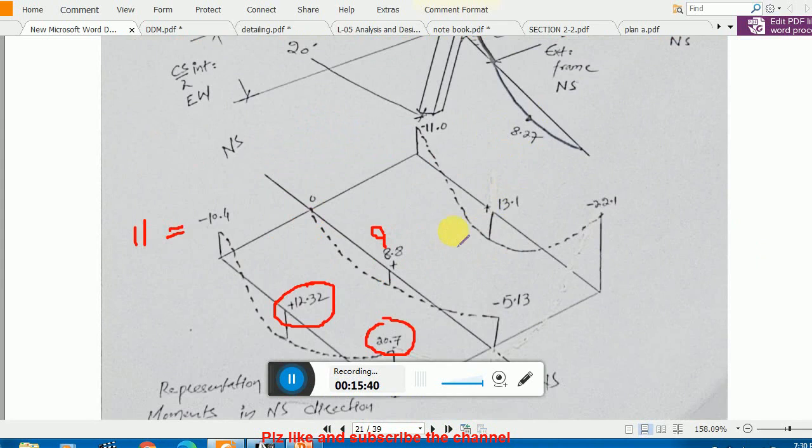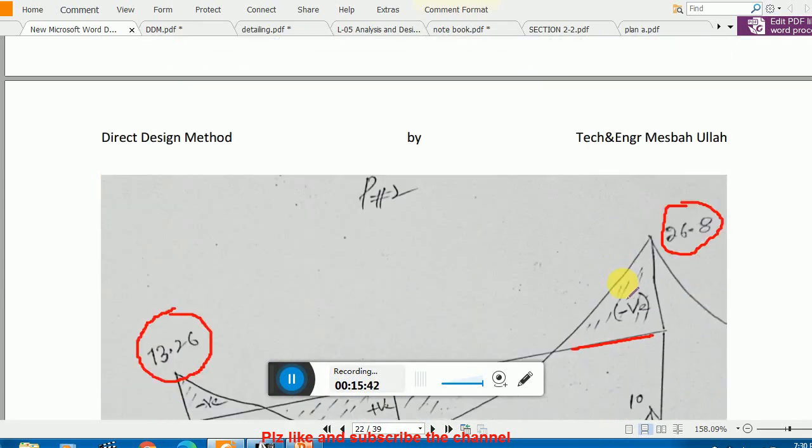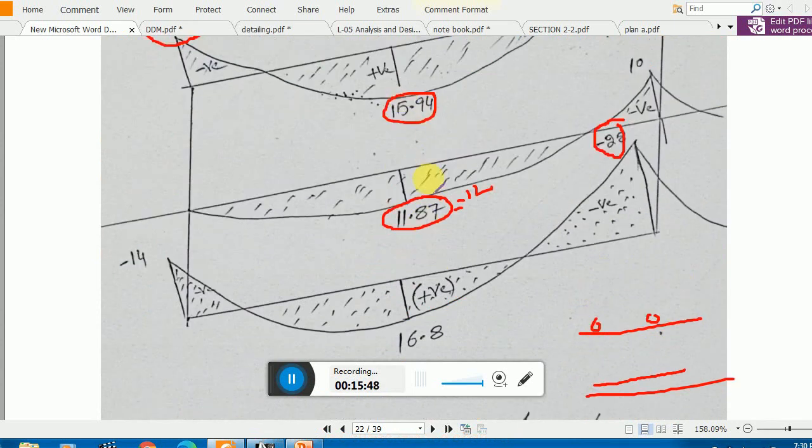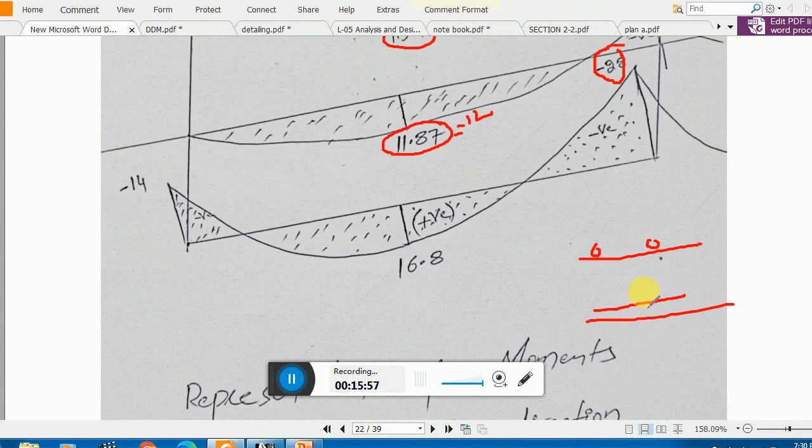Remember, those bars which are provided for this movement, and the top bar will now be those bars which are provided for this. So this is the difference from flat slab analysis. Remember, this is a very important point: which bar should be kept in the bottom layer while which bar should be kept in the top layer. This is very important, so please understand it.